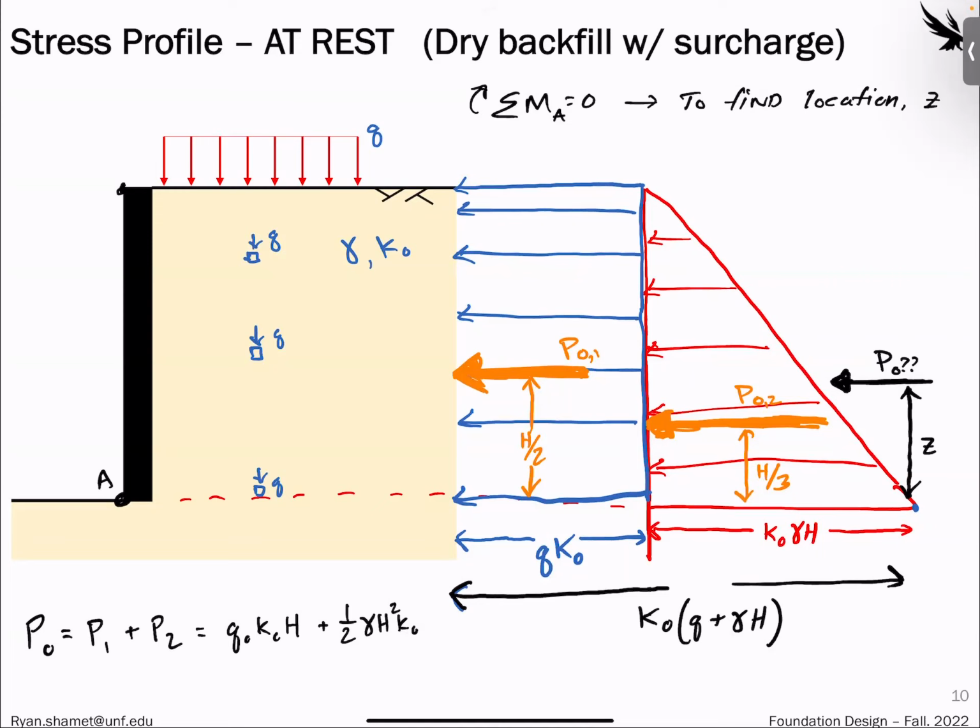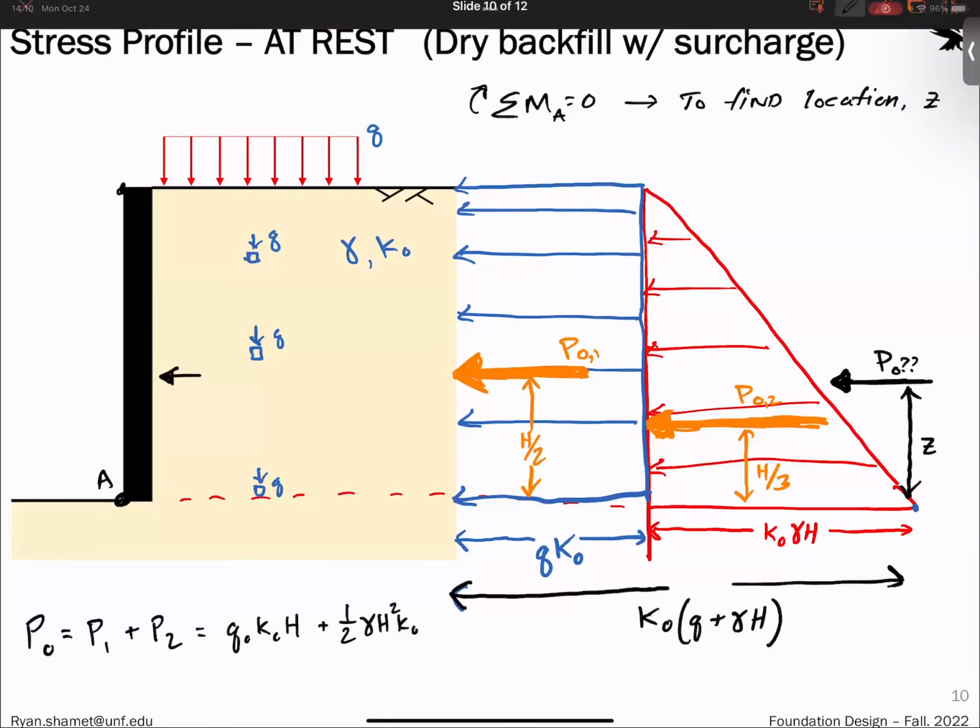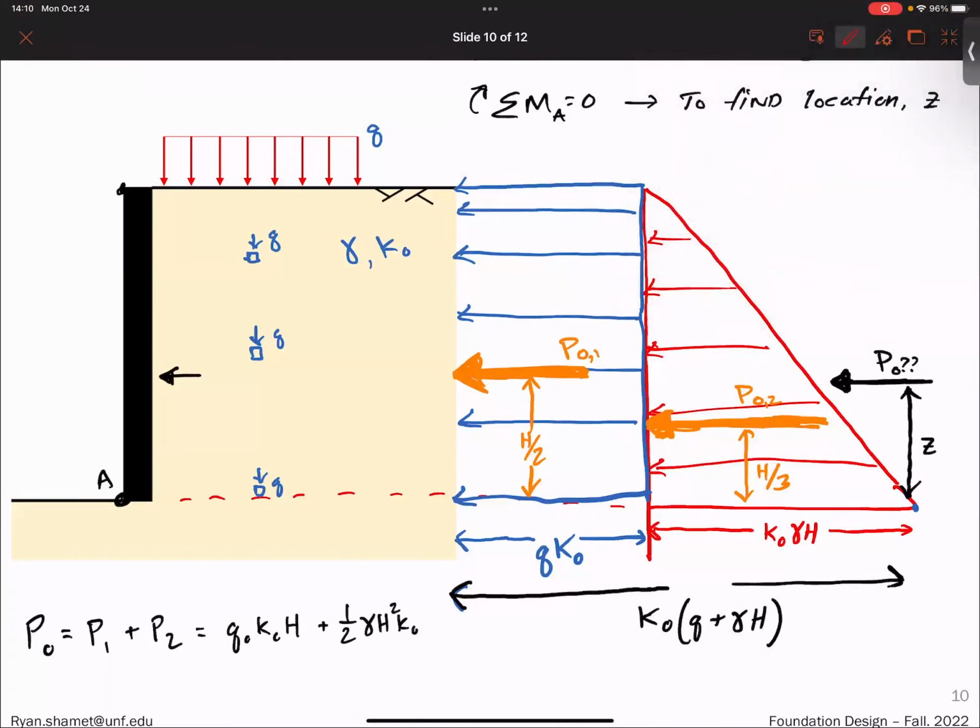Retaining walls, you obviously don't want the soil to bend, so you would look at the deformation diagram and literally draw it, and do all those fun things from your structural analysis class, where you would have a deformed shape. Then you would calculate this maximum deformation and make sure that this wall is structurally rigid enough so you don't have that maximum deformation, or that maximum deformation is acceptable, because if you have settlement horizontally, then you're going to have settlement vertically as well, right? Because if the wall moves out, the soil moves down. So anything on top of the soil is bad.